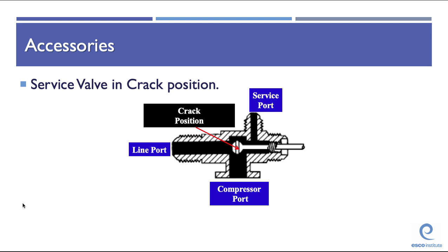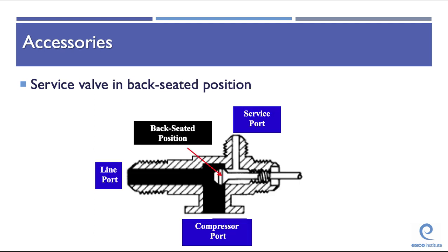Service valve in a cracked position, otherwise known as mid-seated. All 3 connections are open in the cracked or mid-seated position. The line port, the compressor port, and the service port are all open. This is the position for servicing and checking pressures. So most often, you're going to be either in this mid-seated position or in the normal run position.